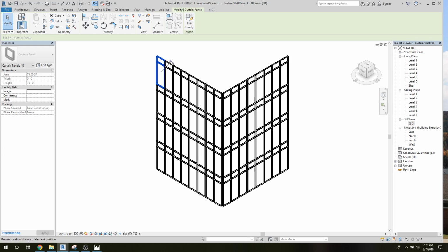That way we won't have to worry about unpinning them, and we'll have a super BIM component that will be all of the curtain wall elements within one module. So any changes we make to, let's say, the extrusion of the profile, that'll populate all of them. So it's a much more efficient way to possibly think about approaching this. So we're going to grab this and we're going to add some elements to it.